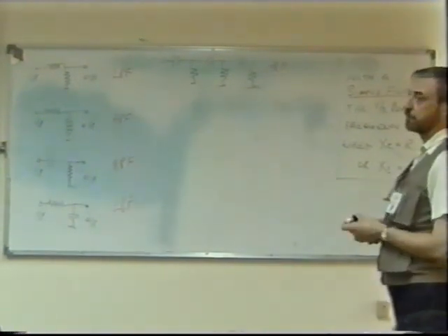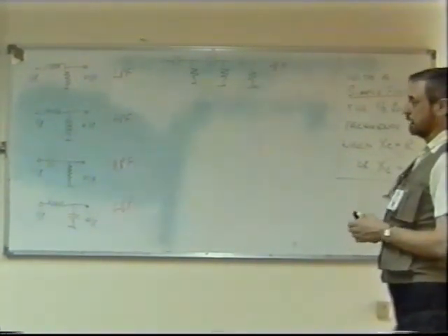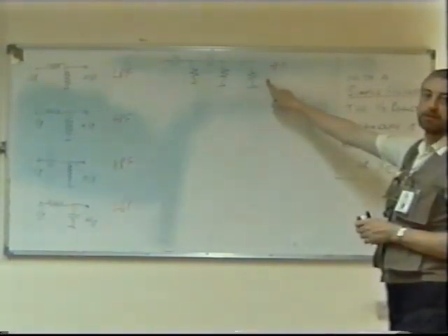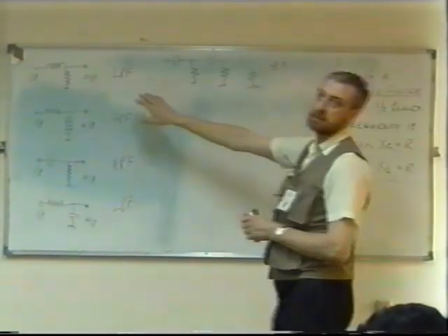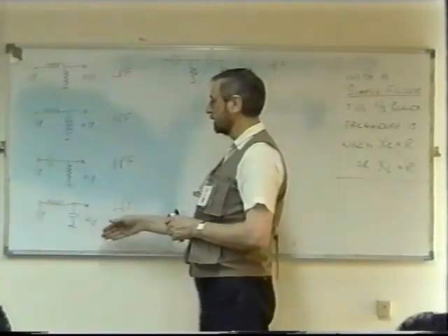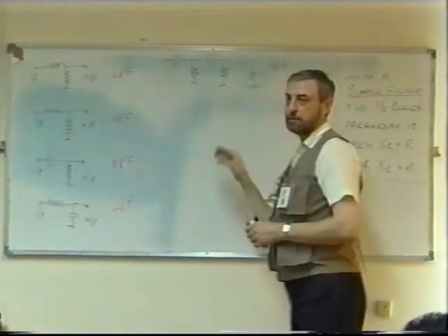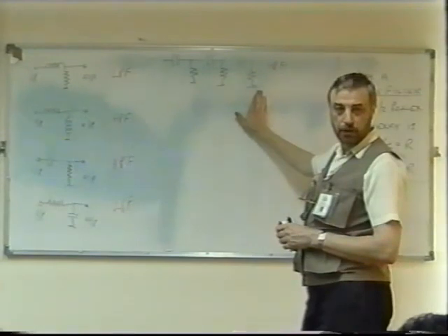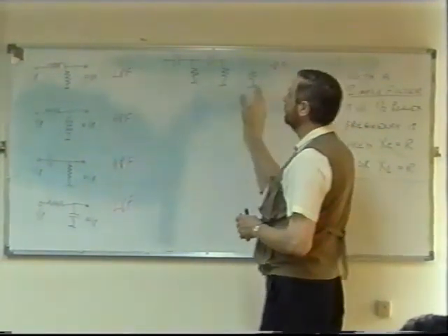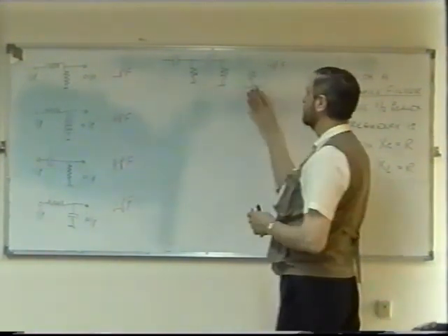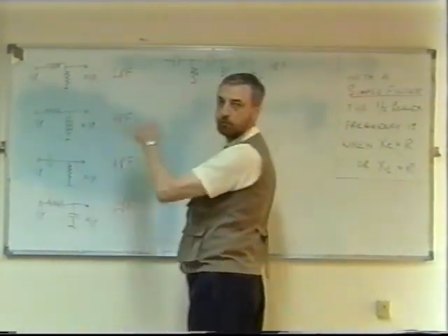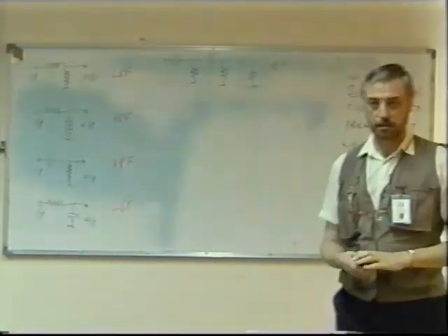The difference only will be when the cut-off frequency is calculated. Here it would be more difficult to calculate what that frequency is going to be. Here it's much easier. If you need any calculation, you're not going to get more difficult than that. But what I'm trying to say is you can get filters which are a lot more complex, but you should be able to just recognize by looking at them that this would be a high-pass filter. It's just a more complicated version of this, like one filter after another in a sense.